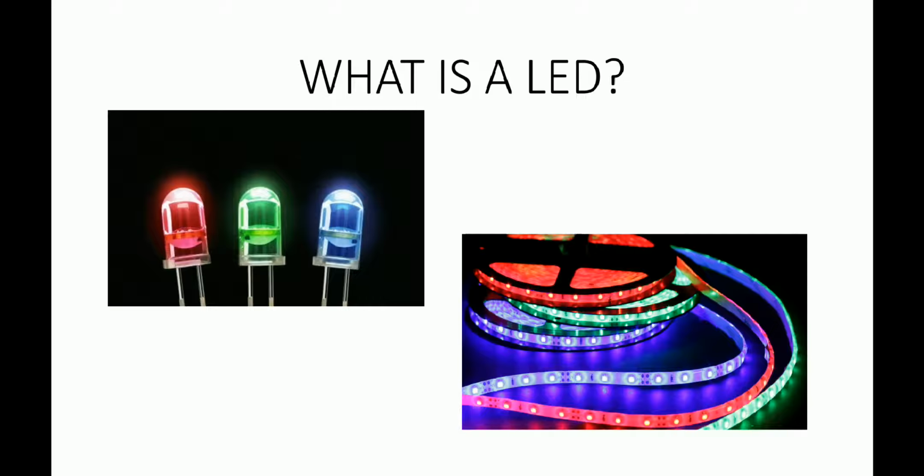LED is basically just a specialized type of diode as they have very similar electrical characteristics to a PN junction diode. This means that an LED will pass current in its forward direction but block the flow of current in the reverse direction. Light emitting diodes are made from a very thin layer of fairly heavily doped semiconductor material, and depending on the semiconductor material used and the amount of doping, when forward biased, an LED will emit a colored light at a particular spectral wavelength.